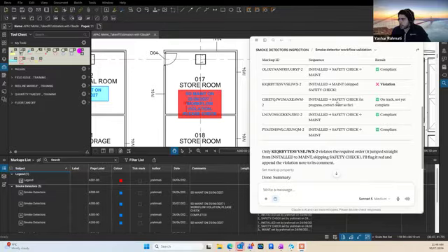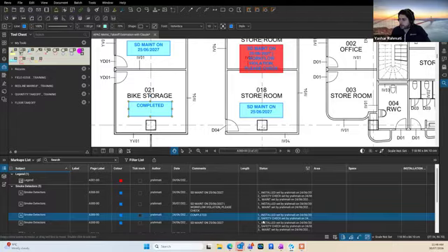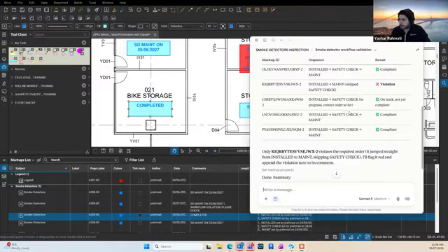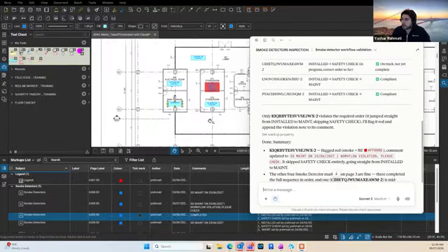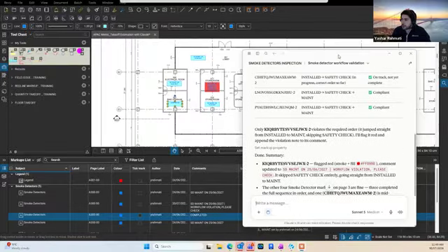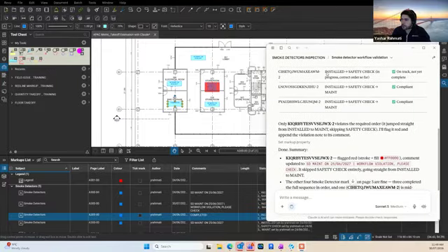Yeah, I can see this one as well, that it is still in progress. So for this item here, I believe we haven't completed or scheduled the maintenance, but since the software identifies that this is in progress, it didn't change the color to red yet. And then from there, we can generate a report. So imagine you've placed hundreds of electrical components using markups. Running a command here can streamline generating reports of electrical devices that have some safety or scheduling steps missing from the list.